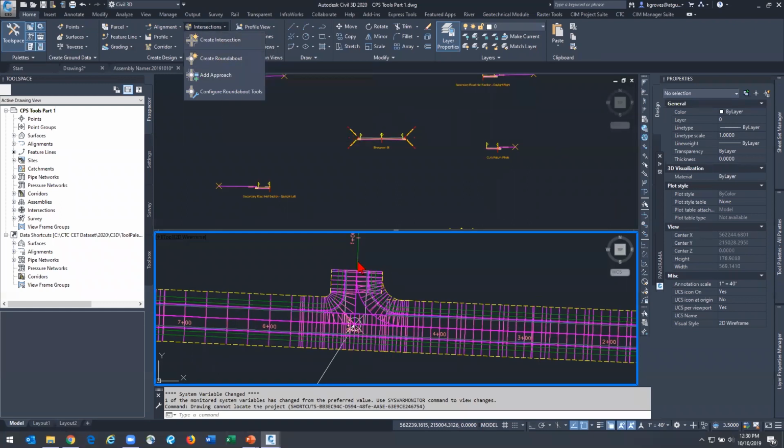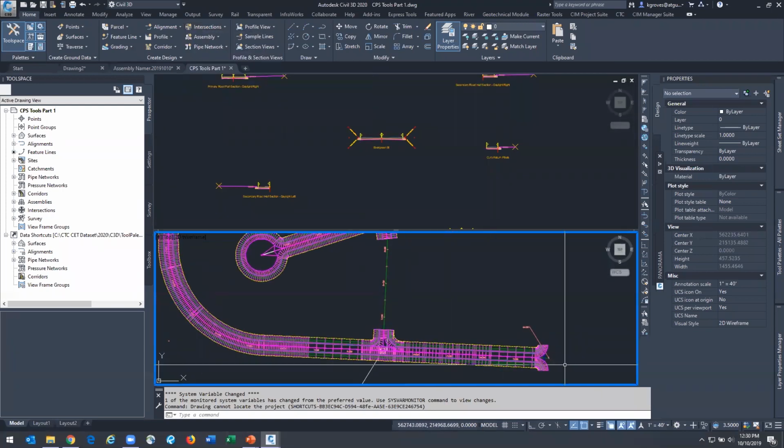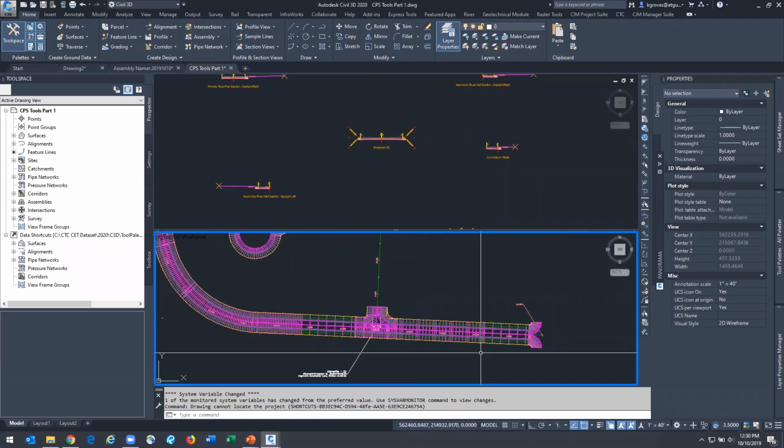So your actual section where you have your corridor roundabout through the intersection wizard, you'd probably want to leave that alone. But for any of your baselines or your regions that are connected to the roundabout area, where you've manually designed your approaches, your straight segments, feel free, I would say, to use these tools on those sections. But that is not something that I've tested.